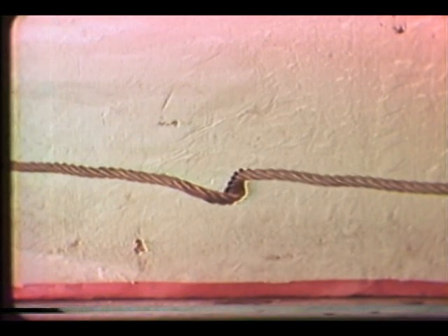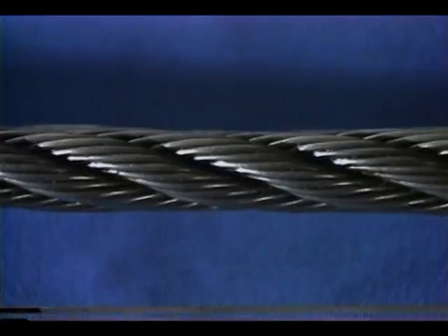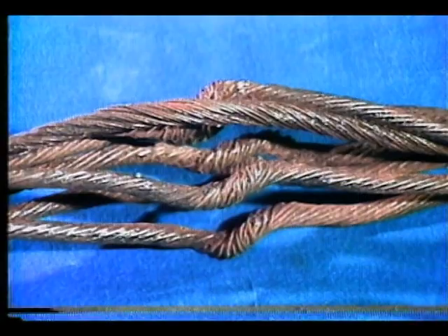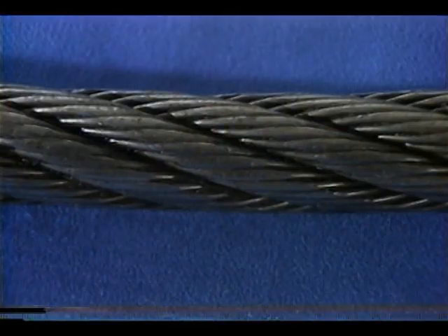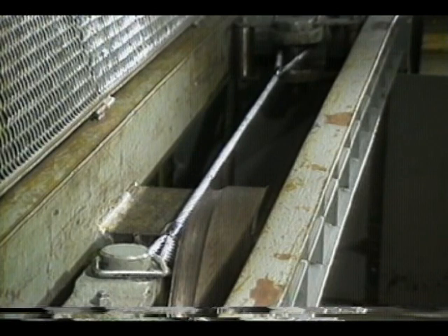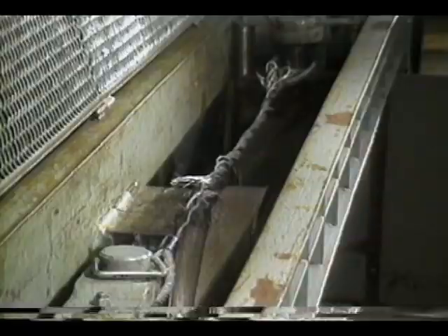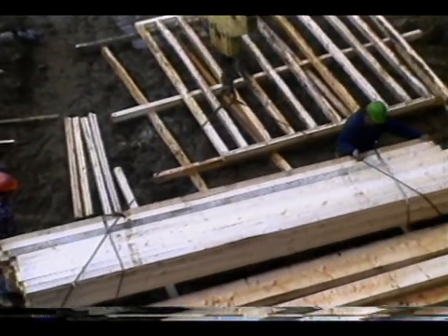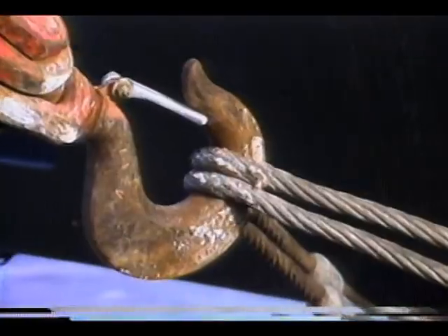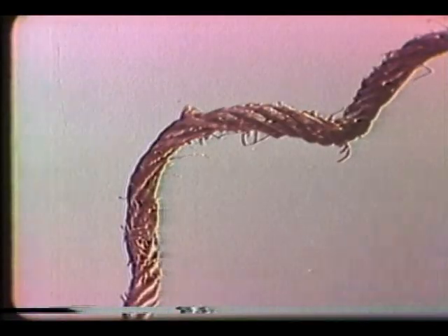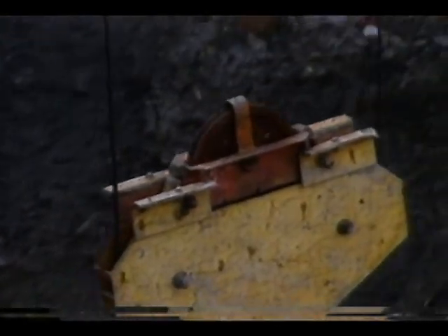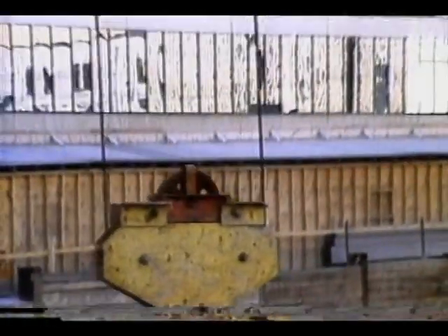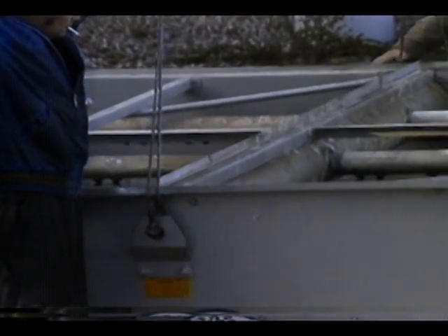Permanent damage and deformation, such as kinks, crushed, flattened, and distorted strands, and uneven wear are the conditions which make a rope extremely susceptible to failure. The weakest part of a rope determines the overall strength of the rope. The weak point may be where the rope is badly worn, where it has a number of broken wires, where the stresses are unequal in the strands, where bending the rope over a sheave creates wear and tear, or where the rope is attached to equipment or loads.